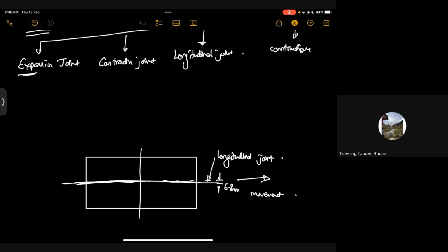Okay, breaking or having a small gap in a rigid pavement along the longitudinal direction is called longitudinal joint, and this is joined by rods basically, and these rods are called tie bars. Similarly, in the transverse direction, यो particular direction ma along the width. अब यो चाहिँ along the length थियो नि हाम्रो longitudinal joint, right? Along the width हामीले भत्काइदिन्छ.